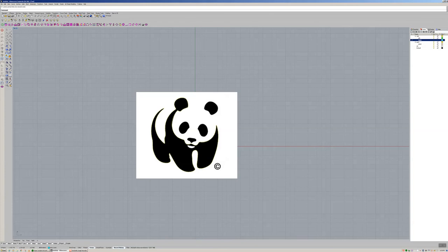So you left click and then you drag around it, right? Yeah, like make a box. And then you join. So left click, you see the box that I'm making here? And then I would select it and everything will turn yellow. Right. And then I hit, here's the join command, it's like a puzzle piece.